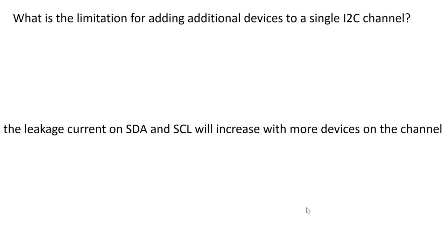Charles actually ran into an issue with this when we were designing the applied portion of this class, because it wasn't clear, when building a system with multiple I2C components, whether we had to add a pull-up resistor on the circuit board, or in our case, a breadboard.